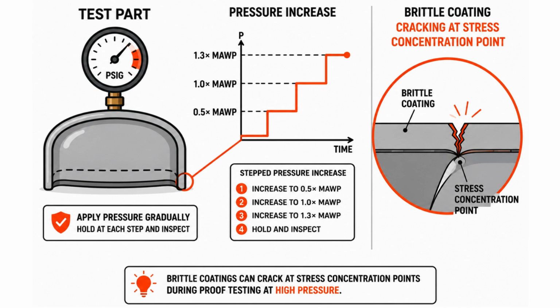The test itself is methodical. Pressure rises to about half the anticipated working pressure, then climbs in small increments, holding and releasing to zero after any step that shows increased strain, watching for permanent deformation. Inspectors can also require a brittle coating on the part beforehand, a coating that visibly cracks under high stress, showing exactly where the real danger zones are before a single strain gauge gets placed.